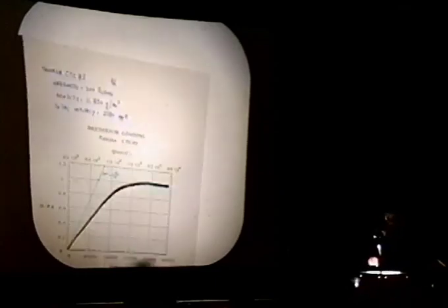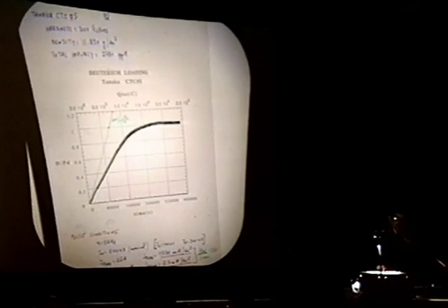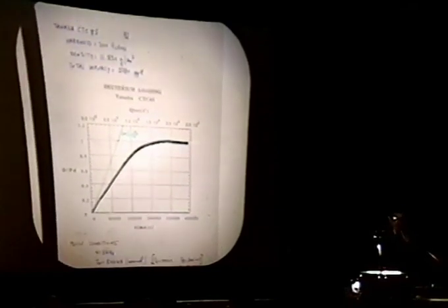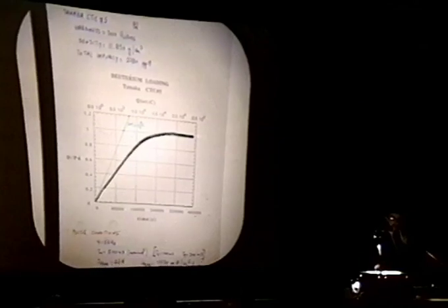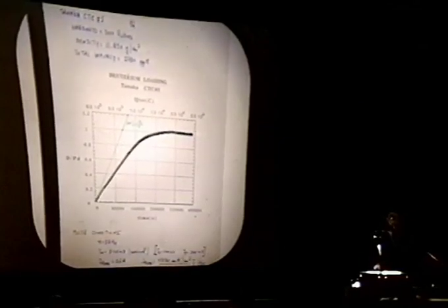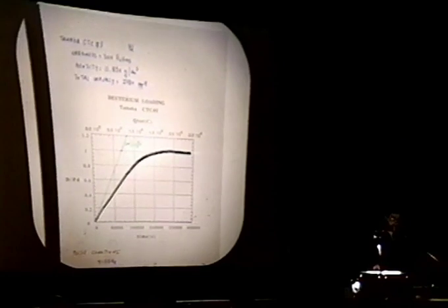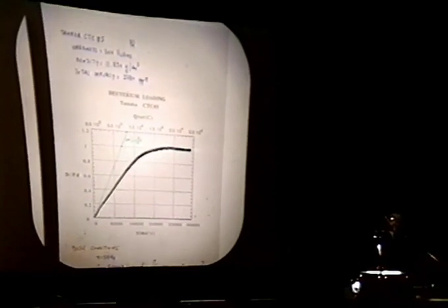In this experiment, the peak current is about 160 ampere. Because the plate is about 12 square centimeters, the peak current density is about 13 ampere per square centimeter. This is the second experiment that we made, studying the same parameters as the gold plate, so it's easier to understand.